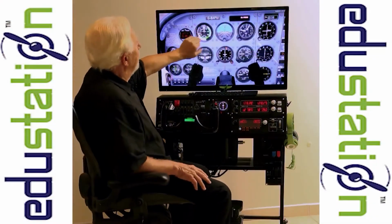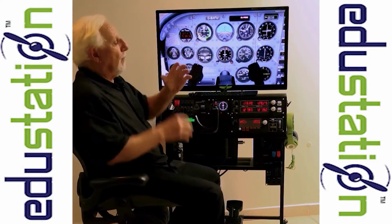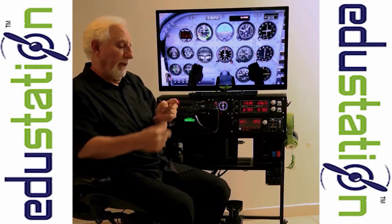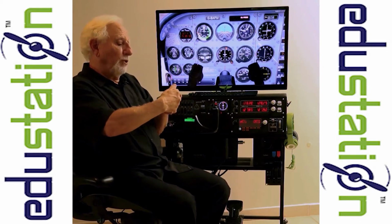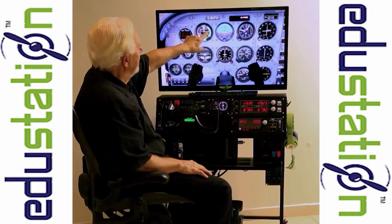The airspeed indicator is telling us how quickly we're moving through the air. And it is powered by a diaphragm. There is what's called a pitot tube outside the airplane. The air rushes into that tube, comes up against the diaphragm, and the pressure moves the needle.